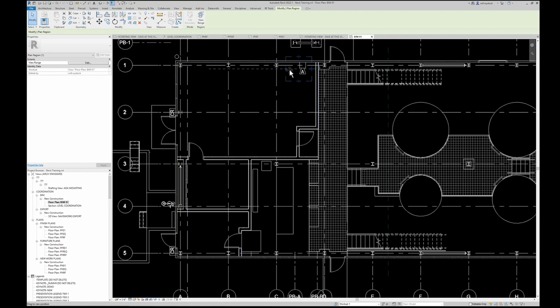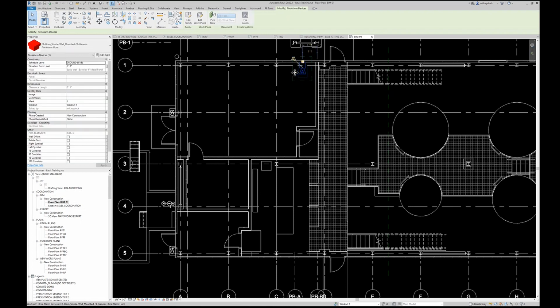I've worked with architects who've done this in the past, but it might be great for finding this little item that you need to do rather than deal with the coordination. But what ends up happening is these things move a little bit, especially across models, because they decided that's the right location for it. You're going to come back later and wonder, what's going on? And most of the time, people don't remember they put these in. I worked on a job before where there were about 30 of these small ones all across the floor plan because they were trying to find all these horn strobes. We ended up spending about an hour trying to figure out what was going on before we realized we just wiped it out and changed the setting to coordination and resolved the problem itself.